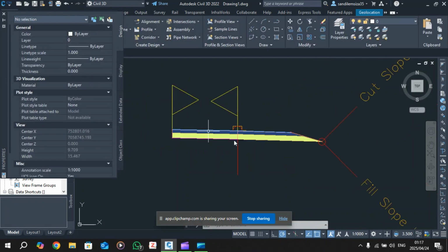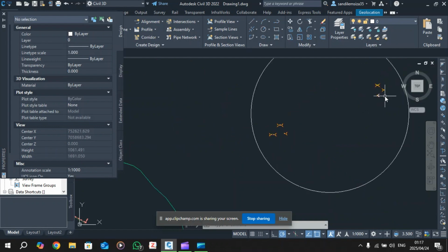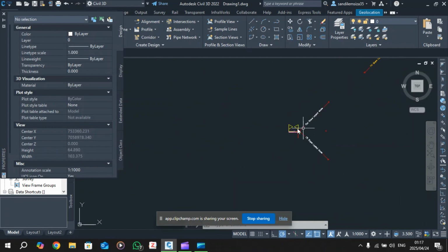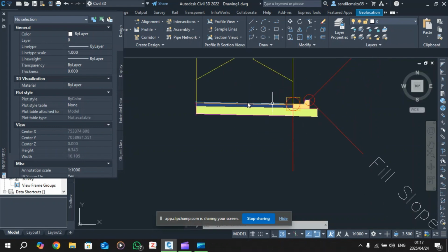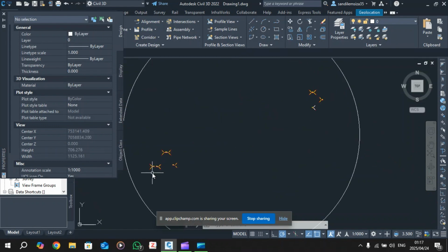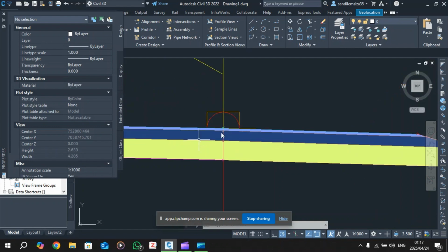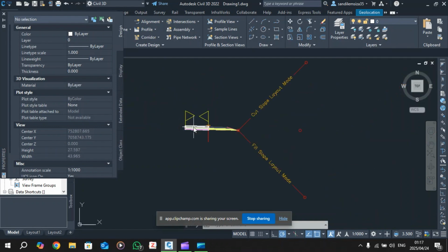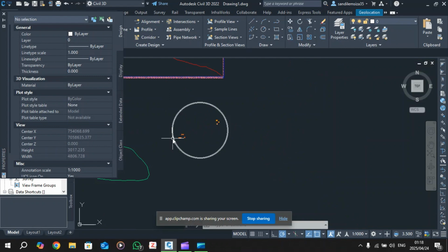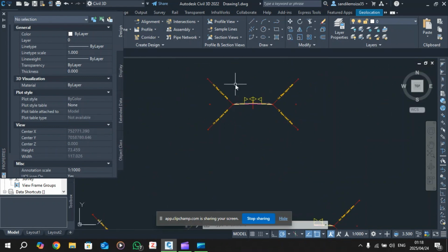So just like that, this is our curb return. If we go back to Civil 3D's curb return, it's this one. You'll see their lane is going up as well as their curb, so same direction. It's very seamless. Let's go to ours, and this is the exact same thing. We just have a shoulder and our cut slope, and again, seamless with our lane on the left side. And I think this is all. Yes, this is all. That is it for assemblies.